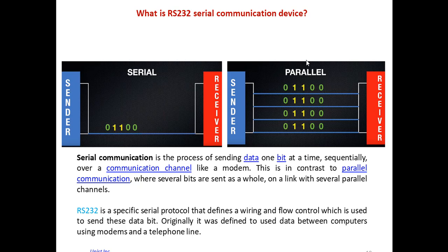This is how we connected to the internet. So if you have an instrument in your lab that has these pins showing on the back, either a 25-pin or a 9-pin, this is an RS-232 serial communication device. This video is going to show you how to communicate between that instrument and LabView, which is basically software on your computer. So basically between this instrument and your computer.